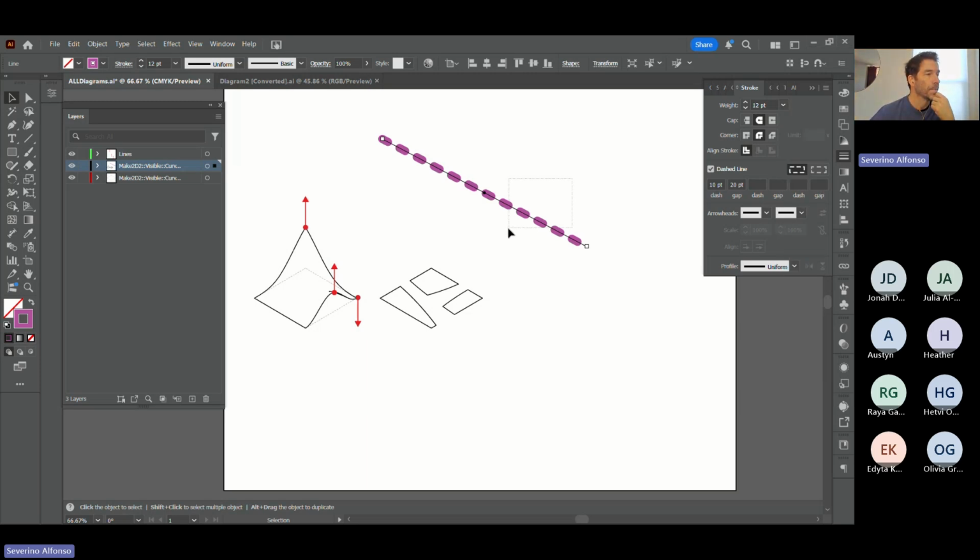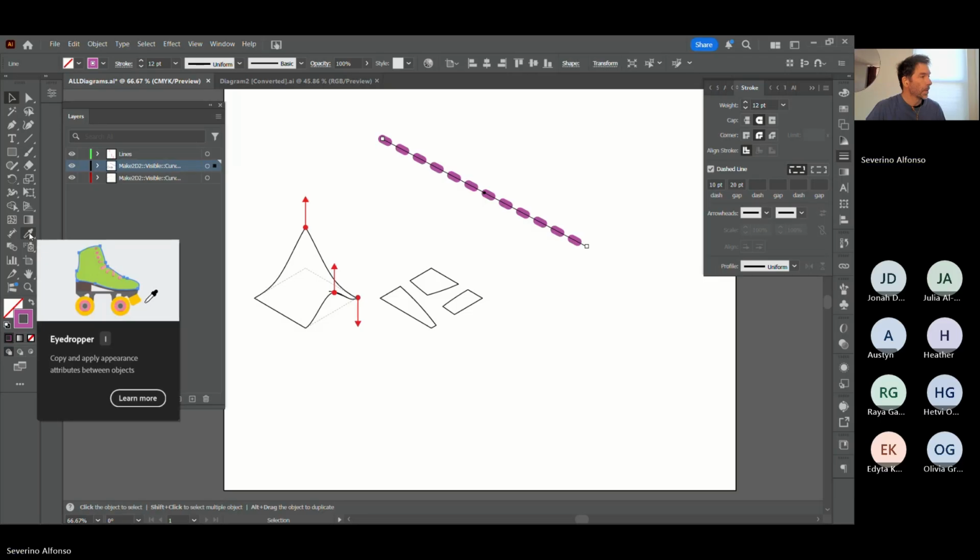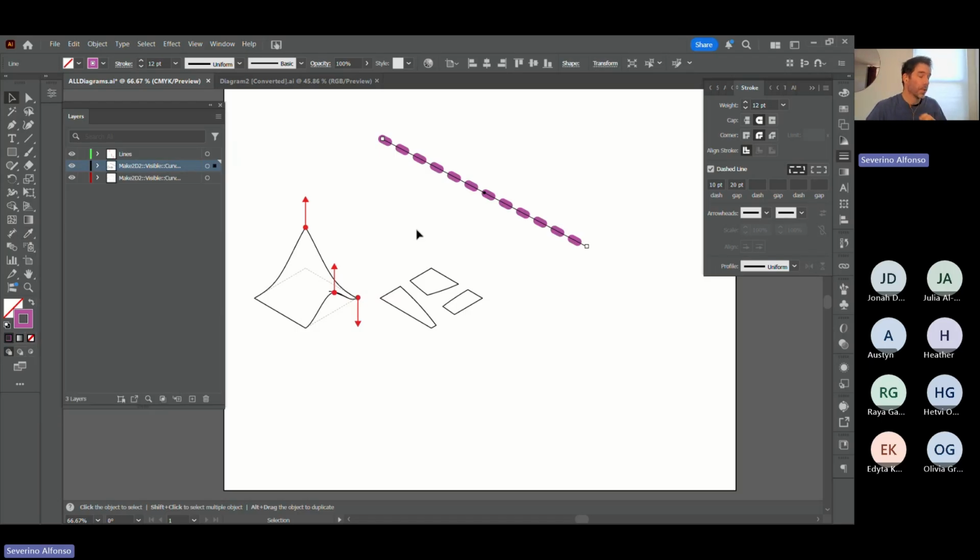And there's always a match properties in every software. In this case, I is the shortcut for eyedropper. Okay, so notice the drawing, you can say, you know, basically match the properties of this second selection. So number one, select the object that you want to change. I shortcut, then go with the eyedropper and the other one selected to the thing you want to match it to. So you select this and it matches the second selected one.